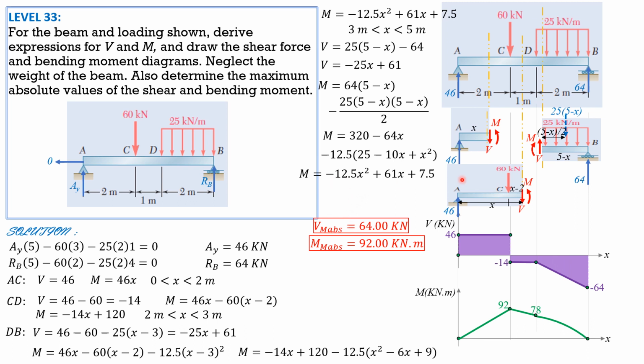So I hope that you gain confidence when you write shear and moment equations at various sections and select the simpler free body diagrams. You just remember the positive sign convention for shear and moment. So when x is 5 in this equation, it is 0 as shown.